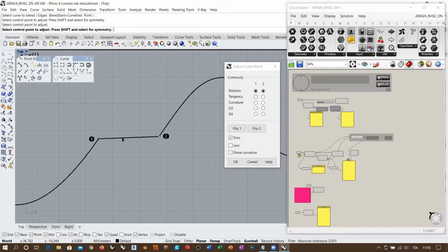And in order to do this, there is no need for additional complexity, because you only need a control point here and a control point here. And so the result is going to be a straight line with two control points, which, by the way, is going to be straight and linear. Okay, straight because of the shape, linear because if we have a control point curve with just two control points, the degree of this curve is going to be 2 minus 1, so degree 1, which is a linear equation. So we have a straight connection with degree 1, straight and linear, right? Which is the simplest connection possible.